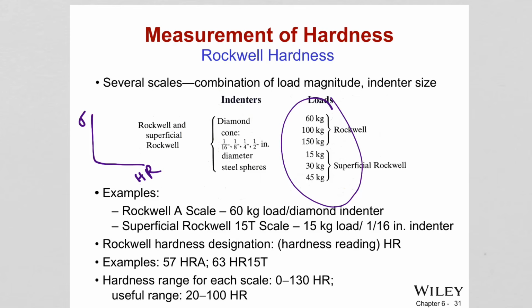Let's say the relationship was like that. Each time you measure the hardness, you can correlate it to the strength. It's like a calibration curve: you first collect that, and then with a given hardness number, you just read off the strength. This is how you can relate it.